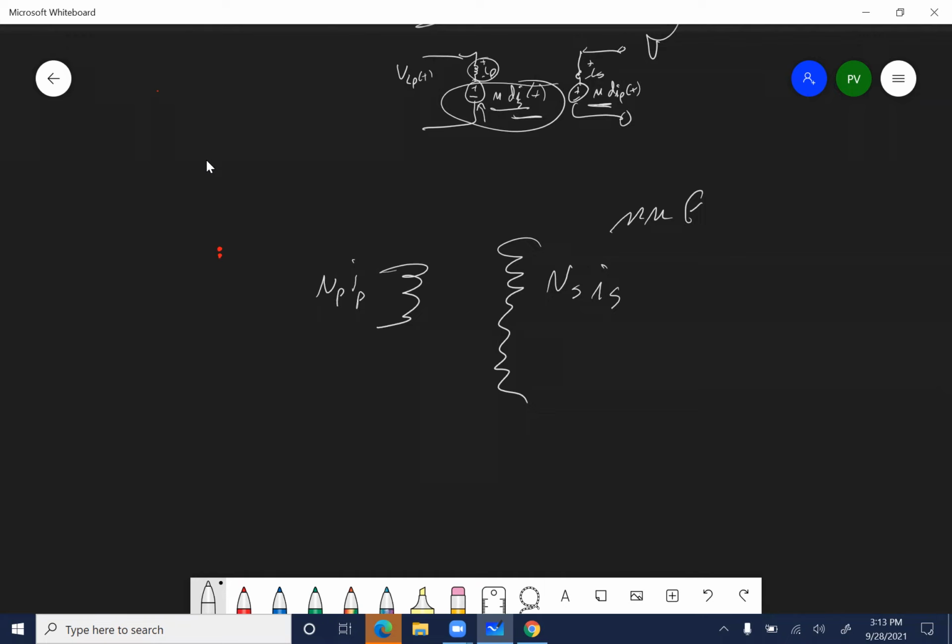How many turns do you probably have to make in order to generate the magnetic field? So the question is how many turns? You only need 1 turn to generate a magnetic field. But if you want to make it so that you don't need 10,000 amps to do anything, with quite a few turns, 500 turns, you can get down in the milliamp range. So for those of you thinking senior projects, if you want to do coil guns or rail guns, you sometimes have to figure out the amount of magnetic energy. That's going to depend on the number of turns, because the more turns, the less current, because it's all magnetics. The magnetic energy depends on the number of turns times the current.